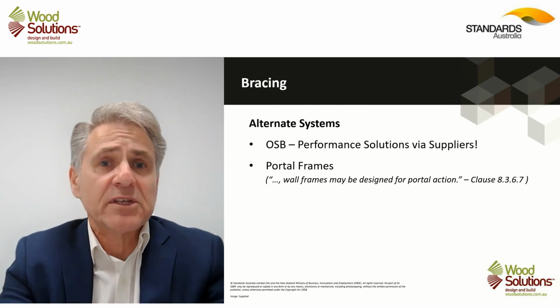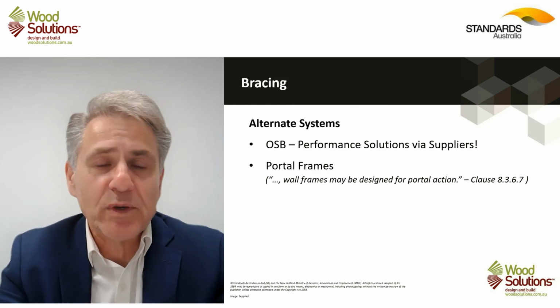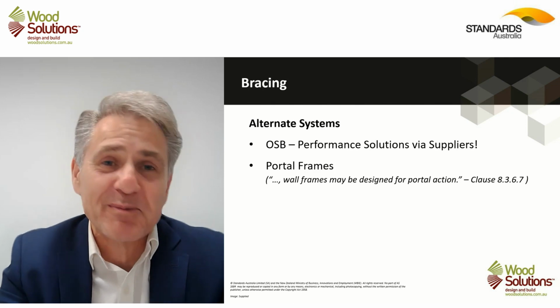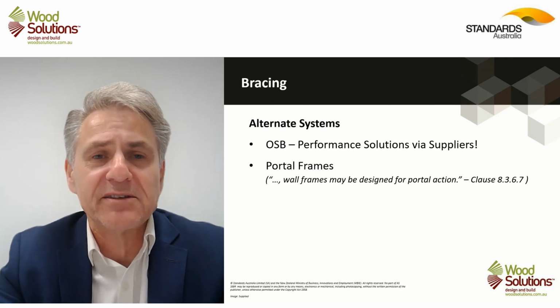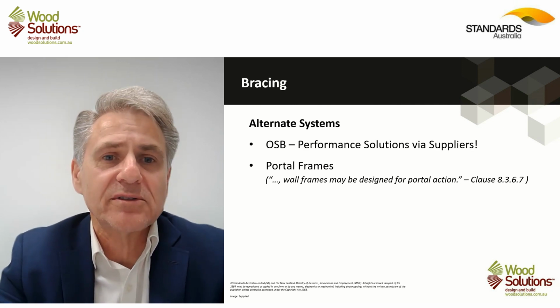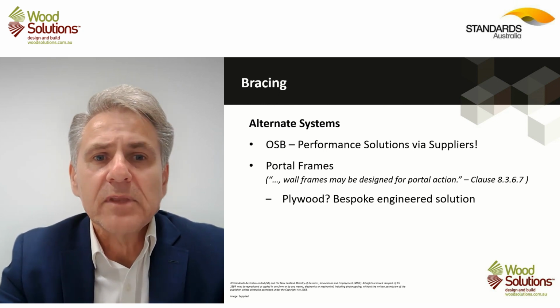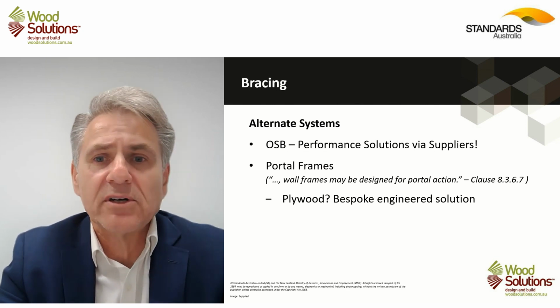There are other systems that are also being used, and these days with people wanting large windows to backyards to see the swimming pool, etc., sometimes you don't have enough walls to get the braces around those openings. So there are portal frames that can be used, and AS1684 does reference that wall frames can be designed for portal action. And there are plywood systems, but that would be an engineered design solution.